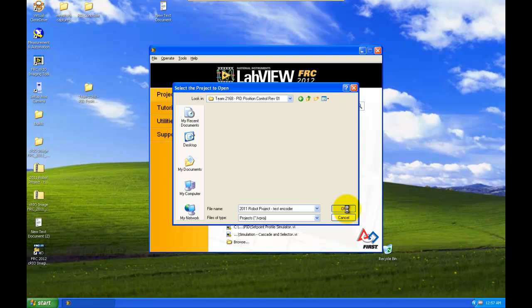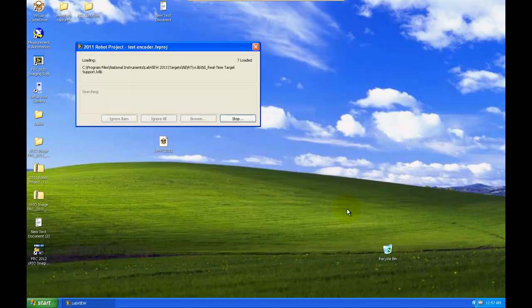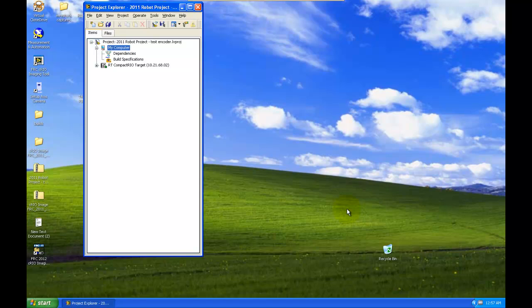Before we start tuning our gains, the first thing we want to make sure is that our hardware is set up and that we have proper command and control. So what we're going to do is deploy this code as is on the C-Rio and use the GUIs that we created to make sure we can manually command the motor and properly read the values from the encoder.